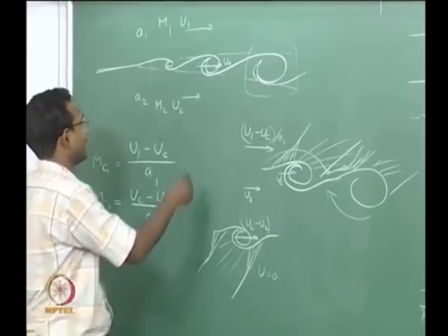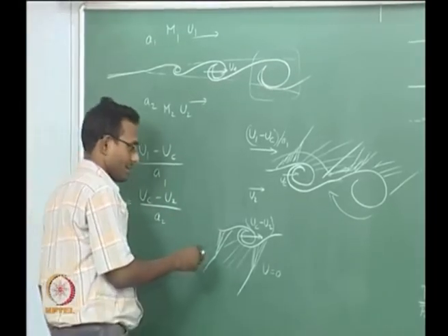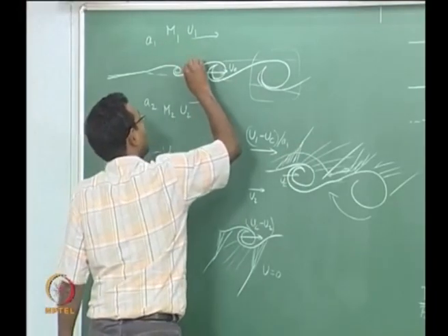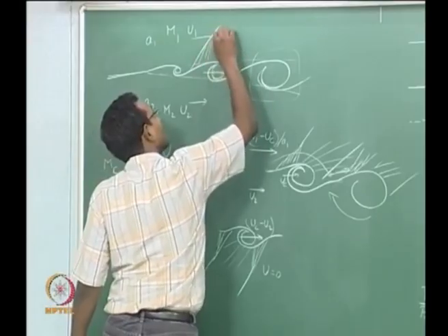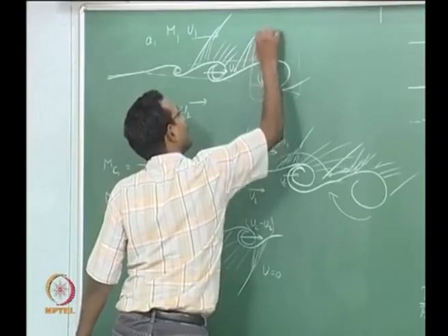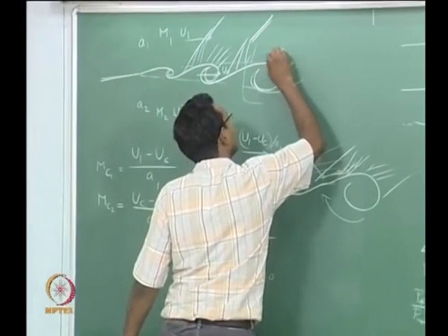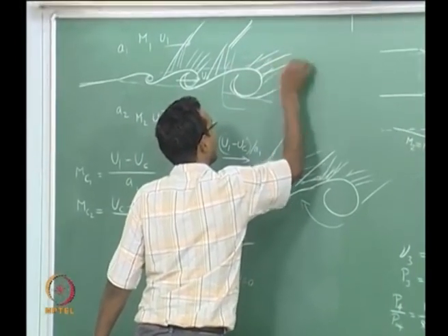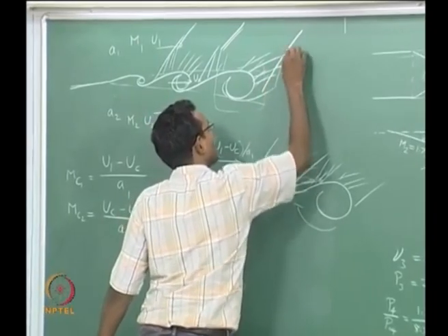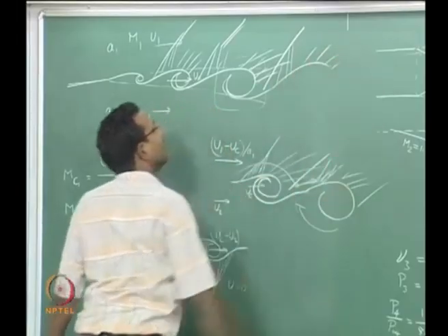So if I look at the whole thing, with a high speed camera we will start seeing this on the top and this on the bottom all together. I will just draw all of them together: shock, expansion, shock, the whole thing together forms a shock, and then expansion again. The expansion will be at a higher angle like this, and then there will be a shock, and again a bunch of compression waves going and connecting with that, and the next expansion starting here.